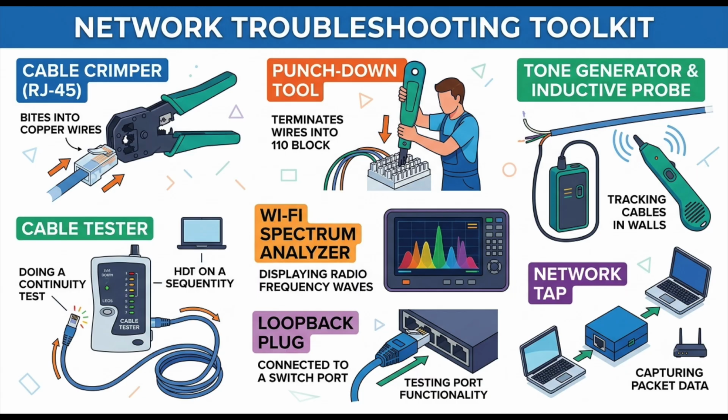The tool is actually spring-loaded. When it reaches the exact right amount of pressure, it fires downward with a loud snap. And the V shape of the groove is what actually cuts the insulation to make the copper contact. Exactly. The groove displaces the plastic insulation, wedging the raw copper tightly against the metal. And the best part is that the punch-down tool has a tiny scissor blade on one side. Oh, neat. As it punches the wire into the groove, it simultaneously shears off the excess tail of the wire, so it gives you a flawless, flush termination in just a fraction of a second.